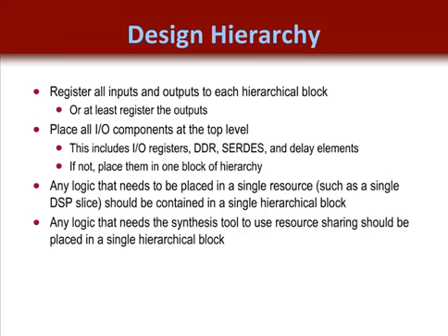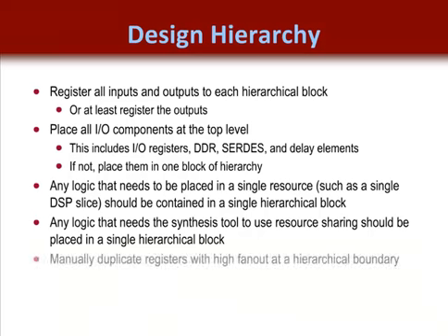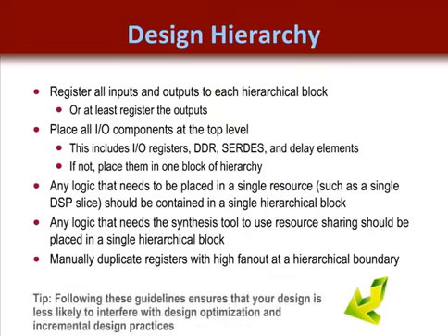Recall that resource sharing is recommended to be turned off, but if you decide that your synthesis result with a component is best left on, then isolate that logic into one hierarchical block. Also, manually duplicate registers with a high fan-out net when it's at a hierarchical boundary. By following these guidelines, it is far less likely that your chosen design hierarchy will interfere with design optimization and performance.